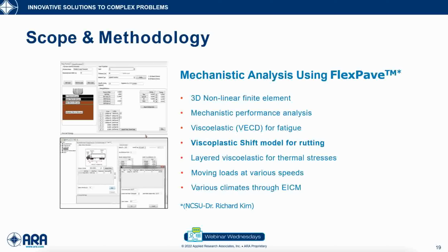To explore whether these base layer properties are affecting rutting or not, we need to do a mechanistic analysis, just basic solid mechanics analysis, but using 3D software. It's called FlexPave. It's a 3D nonlinear finite element software. It performs mechanistic performance analysis. It incorporates viscoelastic continuum damage models for fatigue cracking, so there are nonlinear and fatigue models in there.